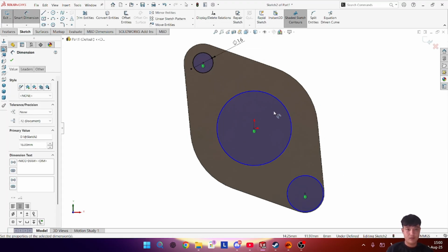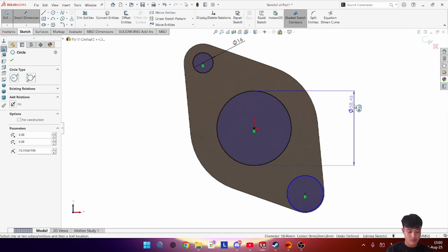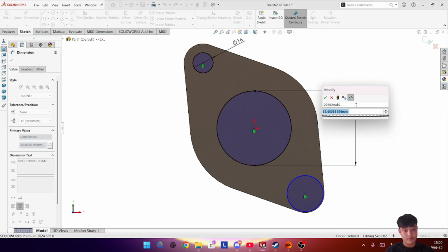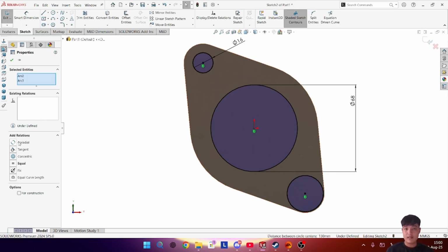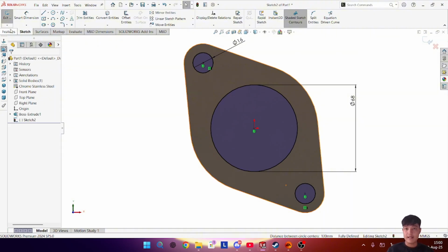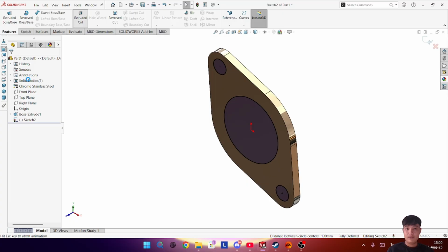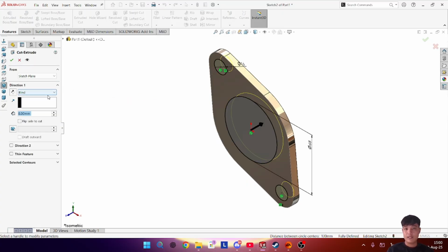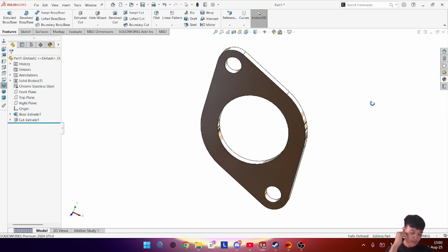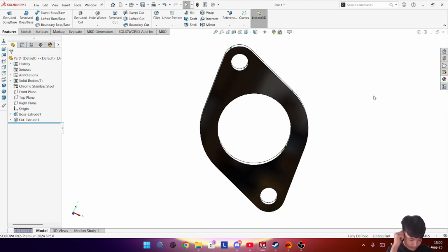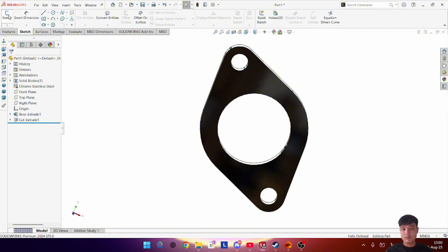Go to feature and select extrude. Now see. Now select here either keep blind and take the 8 millimeter. These circles are equal. Okay. Choose again this surface, sketch normal, and I draw one horizontal line. Okay. Exit. Now select the center line and make relation horizontal. It should be horizontal because this is the reference because we need to create multiple number of patterns.